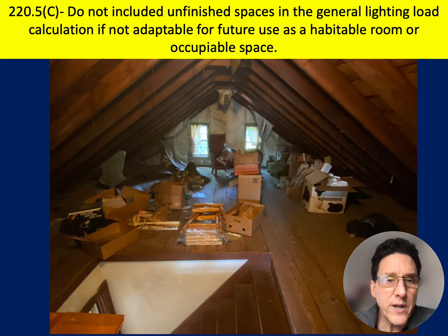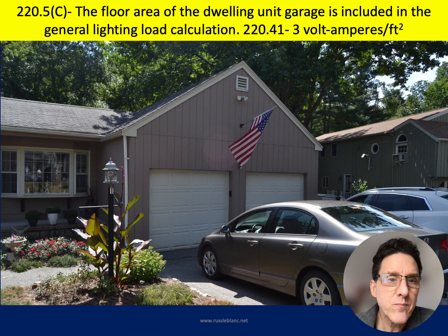I would not include an unfinished attic like this. This unfinished space, it has a floor, but this would never be adaptable as a habitable room or an occupiable space. You don't have the headroom. There's probably not ventilation. So I wouldn't include it. I would include the garage, though. An attached garage, I would absolutely include it. There is lighting there. Include it in the floor area with the rest of the house.